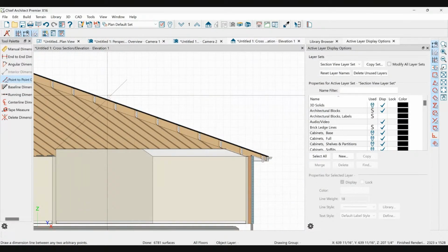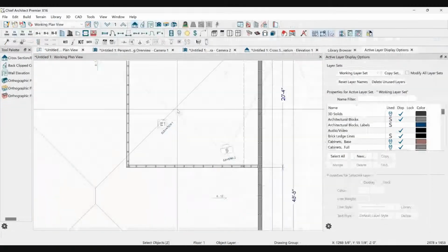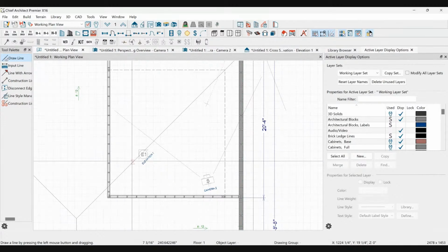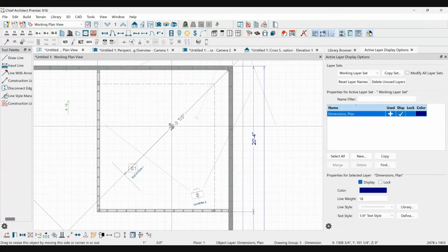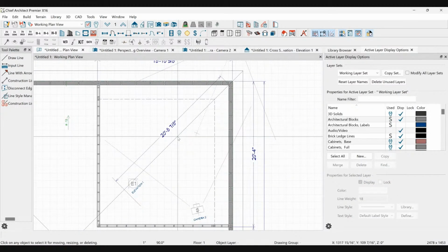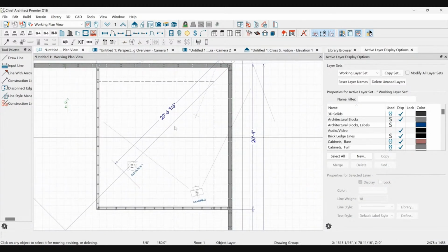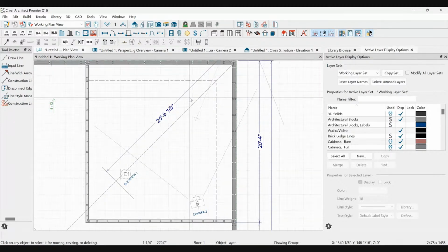But frequently what happens is that unbraced distance over here, look at that, that's 19 feet horizontally. Okay, so look at the plan. If I can brace here to my wall, that's great. But I've got this whole unsupported hip, which is 20 feet long. See that? So this is a situation where if I was engineering this, I would say, unless you're willing to do a weird 45-degree beam thing and get closer to supporting this, or do a special detail on the edges, or, I mean, there's always an infinite number of ways to solve the problem.